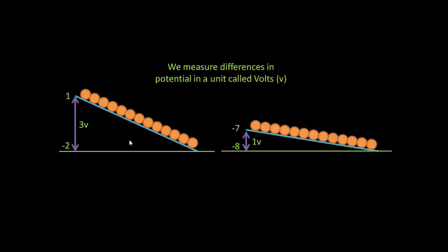I know this sounds silly right now, but you would not believe how many people later on down the road are working inside of a tube amplifier and they cannot grasp this concept. That if you had, let's just say this end was at 100 volts and this end down here was at 97 volts, that the difference between them is really 3 volts. And thus whatever is going across that board is 3 volts. Sounds simple, but people mess it up all the time, I promise you.